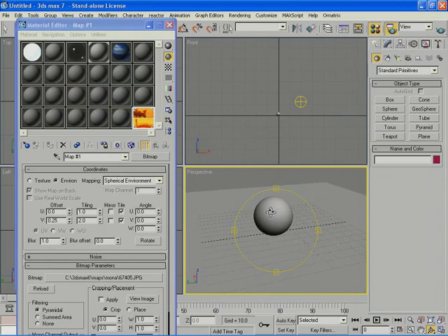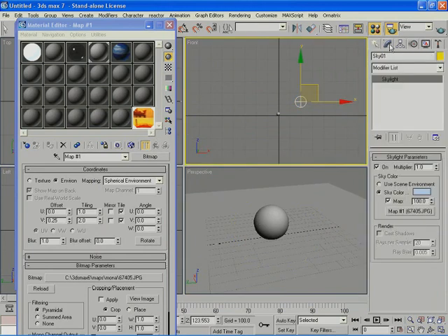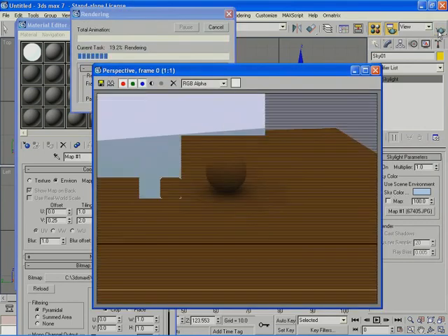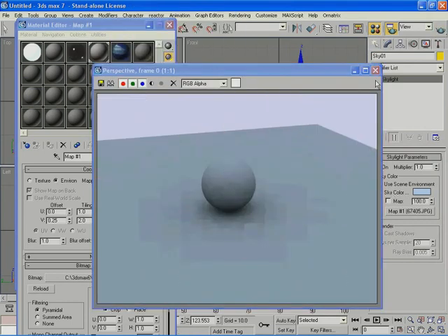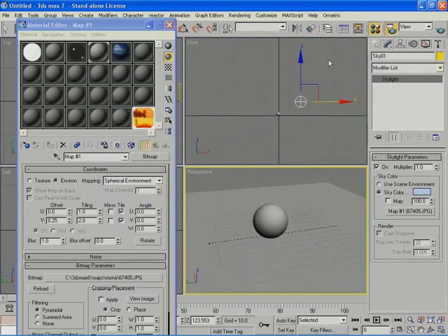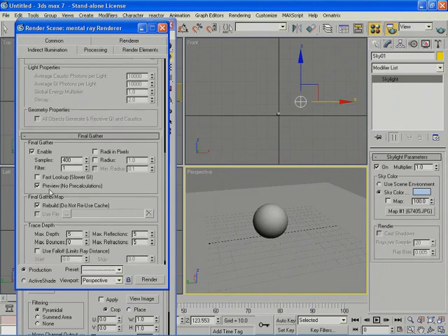Okay, so this is what I get. Now, of course, to fix the samples, I would go down and uncheck preview. Now, before I uncheck preview, I can also work on the radii of my samples, because if I don't choose any radii, the samples are going to be really chunky with the preview mode. If I check radius on, here I'm going to go to 10 as the minimum radius. The radius is going to be the size of that splotch that you see here. If I decrease the radius, the size of the sample is going to decrease, and therefore I'm going to get a higher resolution.